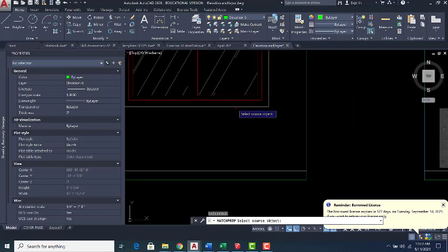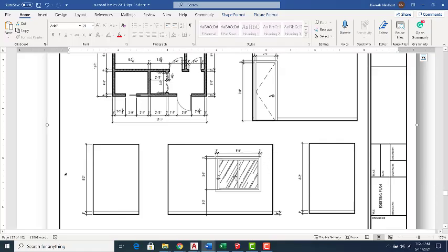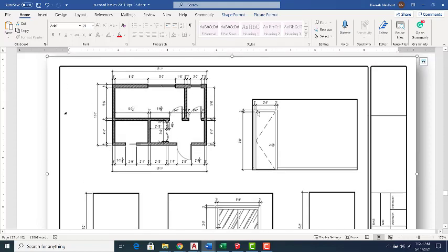Yes. How much was the molding for the door? It's not standard. It depends on the situation. Here, I told you guys it's 3 inches. Same as for the window? Yeah, I mentioned they both are 3 inches. I guess usually they are 2.5. Depends. If you go to old houses, the fancy windows, sometimes they go even maybe 4-inch, because the ceiling is high and the molding has lots of detail, so they go with the bigger one.